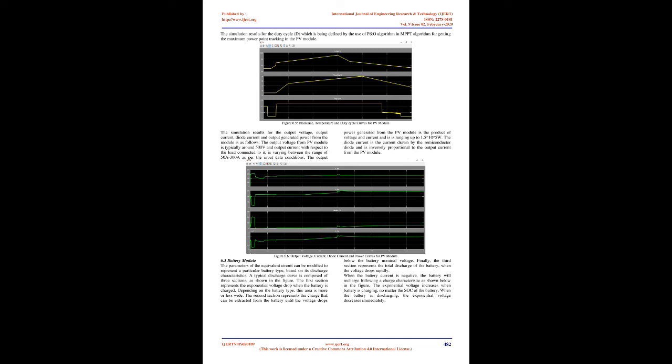E equals E0, minus K asterisk Q0 slash (Q0 minus Q), plus exp(BQ), (2). The variable Q represents the actual battery charge and the variable Q0 is the rated battery capacity. The SOC is therefore the relation Q/Q0. The actual battery charge is modeled by integrating the battery current and adding the start charge as shown in the equation used in the figure below. Figure 4.6, circuit diagram of the battery model with a nonlinear controlled voltage source.